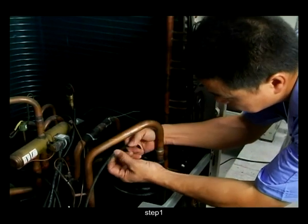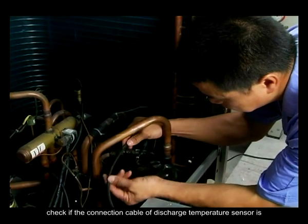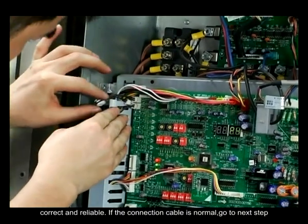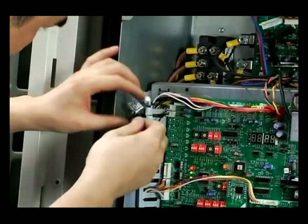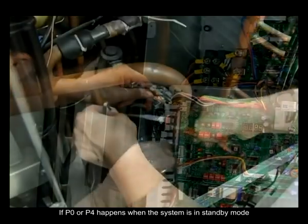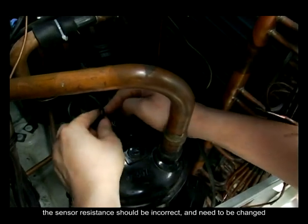Step 1. Check if the connection cable of discharge temperature sensor is correct and reliable. If the connection cable is normal, go to the next step. If P0 or P4 happens when the system is in standby mode, the sensor resistance should be incorrect and need to be changed.